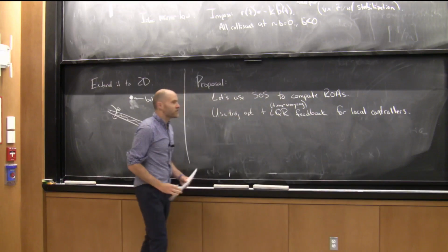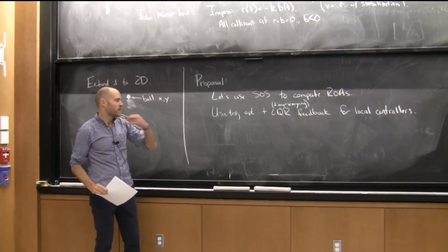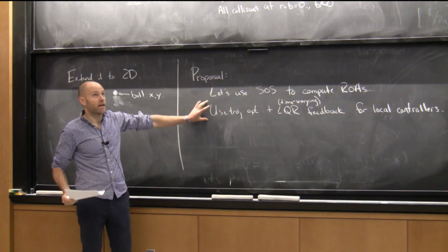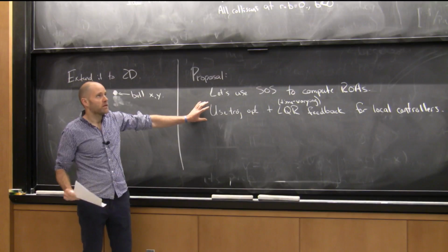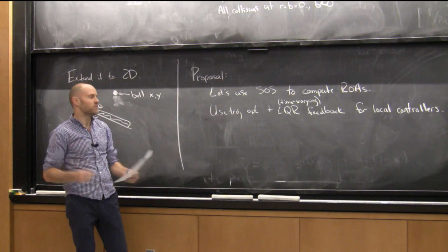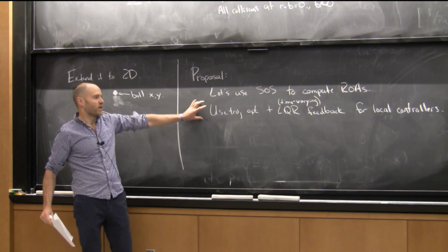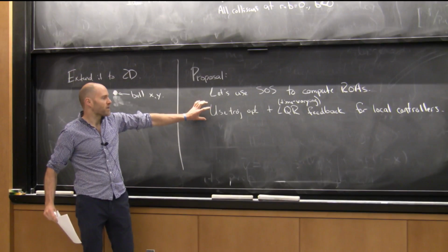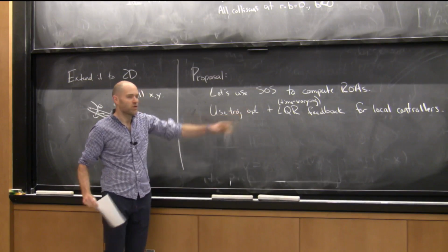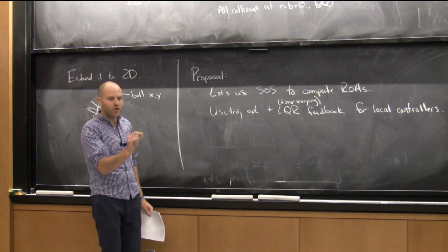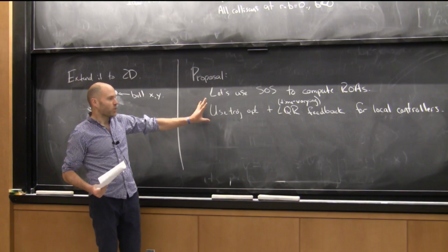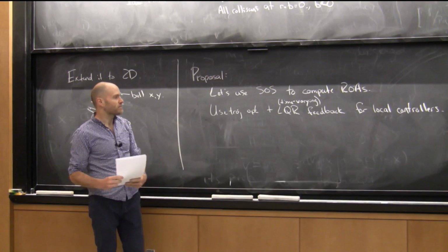Okay, now that gives us a step up on the older approach. If we're willing to do this, then there's no cleverness required to come up with the feedback controllers, but if you have been clever and you have a good controller for trotting on Big Dog or whatever, you should use it. But this has the nice property that, for a particular initial condition, I could do trajectory optimization and LQR and come up with a local controller that works in whatever part of state space I want, and it works for most arbitrary systems, right?